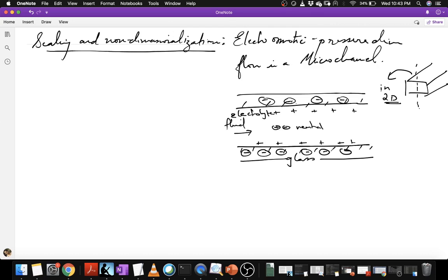So it is in effect shielded from the negative charge of the wall by this positive charge of ions that develops near the wall. This happens even if you take a large channel of glass; you would also have this electric double layer. However, the effect of this double layer is more prominent in microchannels, for reasons which we will see. Normally this layer will do nothing much if you simply apply a pressure driven flow across the channel.